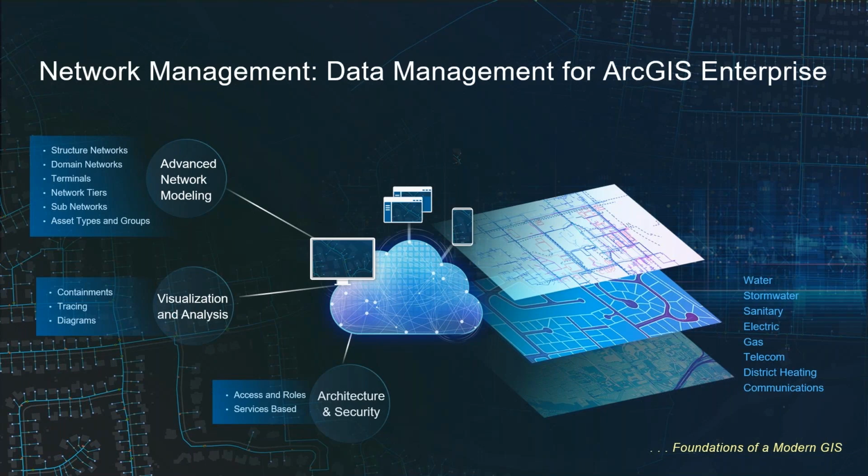The one piece there as well that I think is great to be aware of is that in the geometric network, you had functionality where everything had to be coincident. So all of the geometries basically had to touch to have connectivity take place. The utility network allows you to build connectivity based on a rule set. So you can say this asset or this line or this pipe or this wire is connected to this valve, to this transformer bank over here, and set up those relationships.